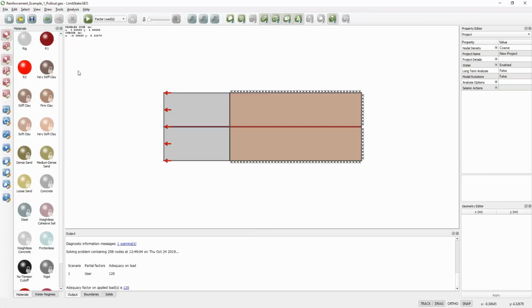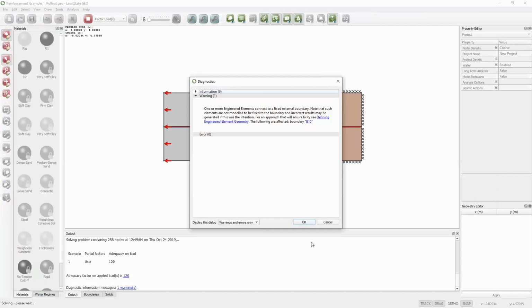What I'll finally do is set a rupture strength here. We'll come back to this a little later. And that is a limiting value on the tensile force within the reinforcement. So if I set that to 60, at the moment it was set to infinity, then it basically says the reinforcement cannot get up to a tensile force larger than 60.